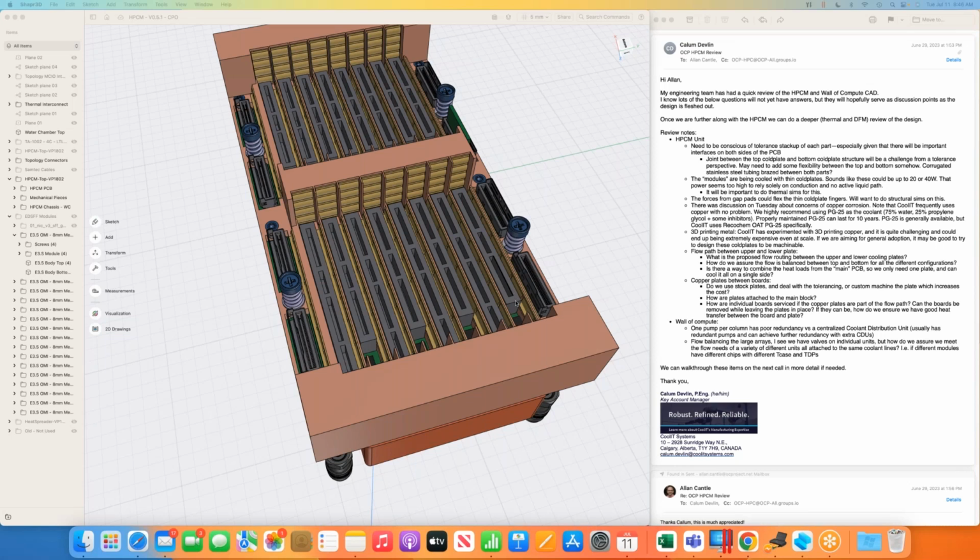They're going to move around a little, and how much do we have, and does the compression piece of the thermal attach soak up the tolerances enough or not? Did I explain that very well, Callum? Yeah, I think that's what it comes down to, is making sure that there's enough play in that mechanical thermal joint to allow the electrical connection within its tolerances as well. Right.